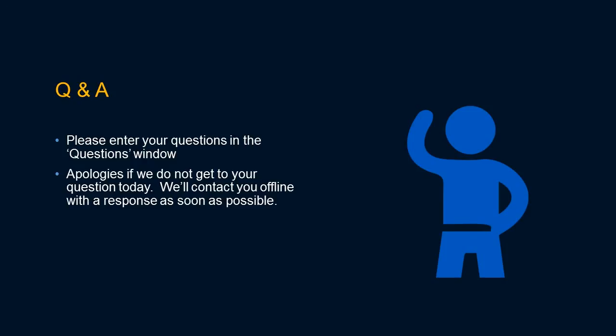For the most part, I think it's safe to say if you needed to run a pulse a couple of 100 feet and you have a good powered pulse, you have no problems. If you want to run at 1,000 feet and you have a nice powered pulse, you don't have an issue. If you want to run a flow meter's mag pickup a couple of 100 feet, now you could start running into issues. So unfortunately, it's not something I can easily give an answer to, because you really need to see the specifications of the pulse generator to know.